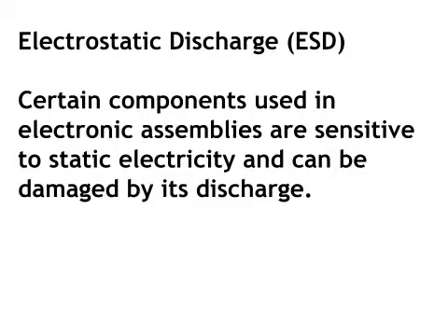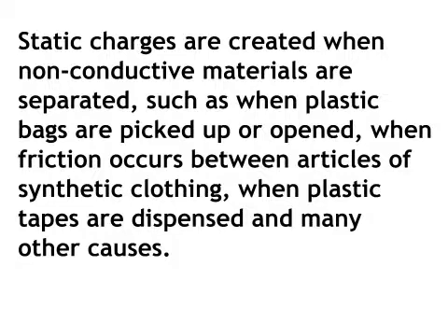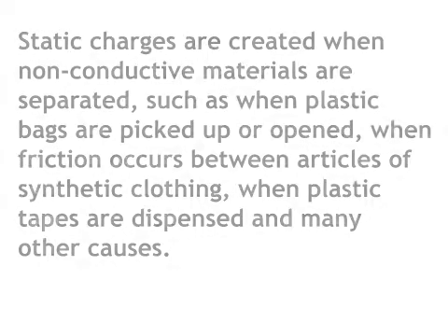Certain components used in electronic assemblies are sensitive to static electricity and can be damaged by its discharge. Static charges are created when non-conductive materials are separated, such as when plastic bags are picked up or opened, when friction occurs between articles of synthetic clothing, when plastic tapes are dispensed, and many other causes.